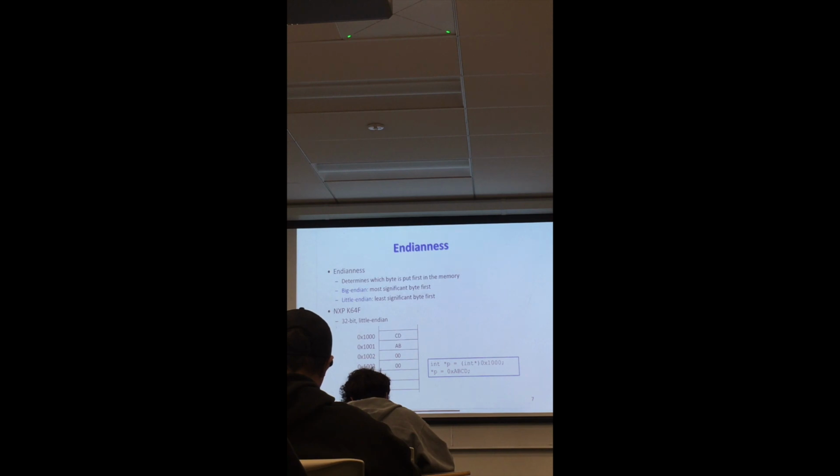All right. So in big endian notation for endians, the most significant bit is located at a lower address. So if your address is like 0, 1, 2, 3, 4, 5, most significant bit would be located at 0, followed by lowest significant bits in big endian implementation. In little endian implementation, the lower address corresponds to a lower significance bit. So that's what we have to understand.